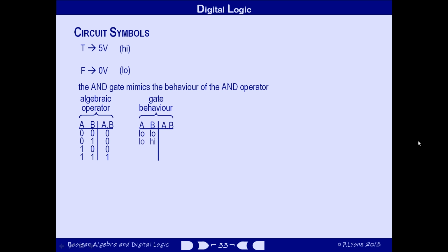The inputs would be a set of voltage combinations, following a similar pattern to the patterns of trues and falses, or zeros and ones as we have here, in the truth table on the left. And its output column would have a series of highs and lows that followed the pattern in the result column of the truth table. Since this is the voltage table for the hardware equivalent of an AND operator, there'd be a true in the last entry, where both inputs are high voltages or trues. And all the other outputs are low voltages representing false. Well, such devices have been produced. They're called gates, and they're commonly available for a few cents at electronics supply shops.